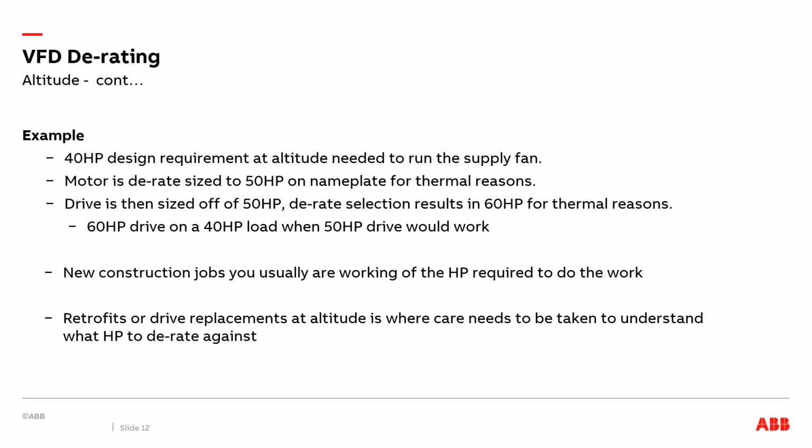So in this example, we're going to be installing a drive on a supply fan at a certain altitude. When we look at the supply fan, the work required at design is that it's going to require 40 horsepower to move the air required. So let's add the motor to the fan, and by looking at this altitude that we're at, the motor is going to be derated to 50 horsepower for thermal reasons.